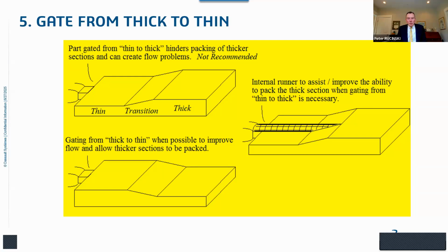Not a preferred approach, because you're going to be adding more material when you don't really have to. It serves no functional purpose other than to get the mold cavities to fill and pack. And then you may also pay a price in increased cycle time, because now that geometry is going to take longer to cool off before you can eject it from the mold.